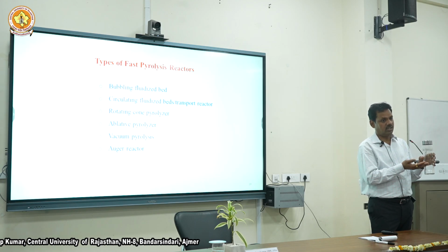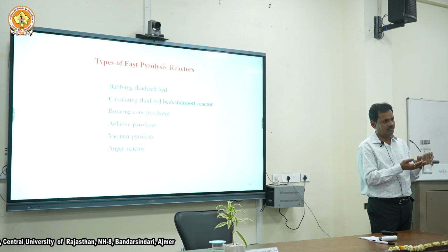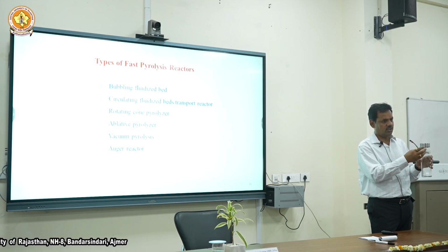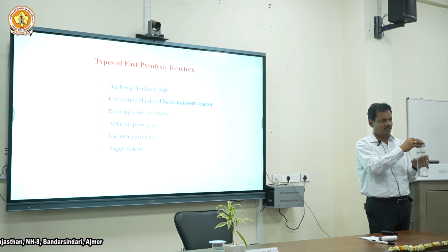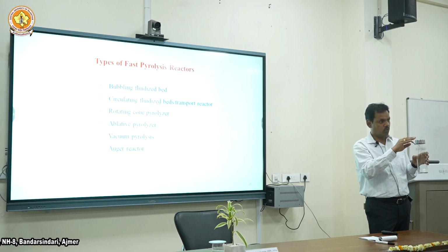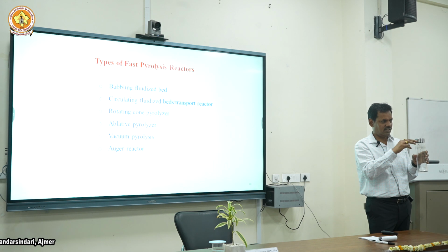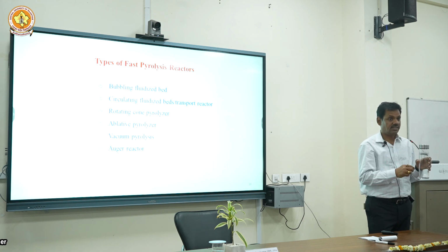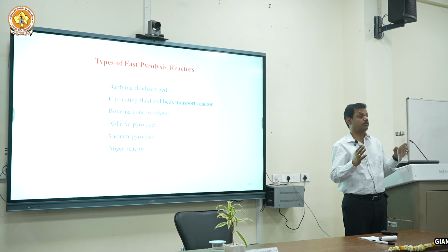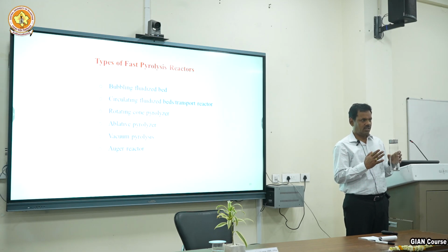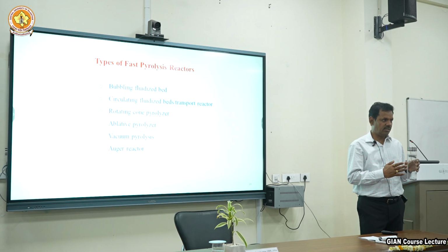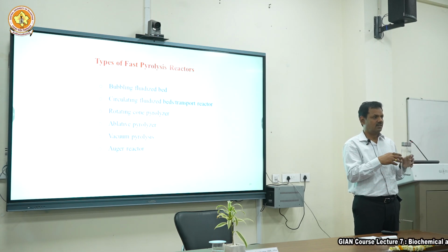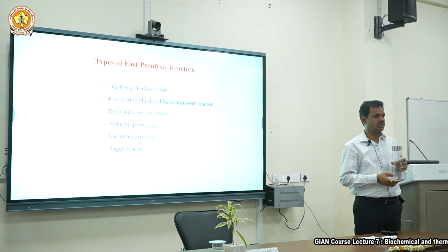From the bottom you pass gas, what will happen? It will just try to rise, right? If too much velocity, it will come out, it is open. And if there is the right velocity, it will look like boiling, right? It doesn't go up and it cannot settle. That right point is called fluidization. It behaves like a fluid. Not exactly liquid, not exactly gas, it's this fluid kind of thing. It's nice mixing and all. So that's how you do pyrolysis, in a fluidized bed.